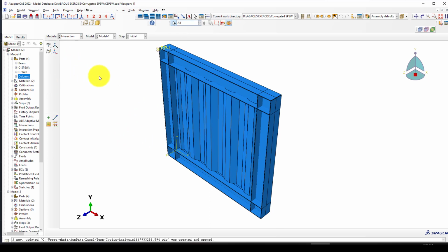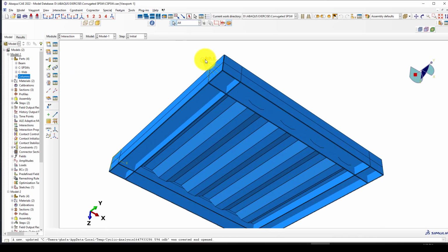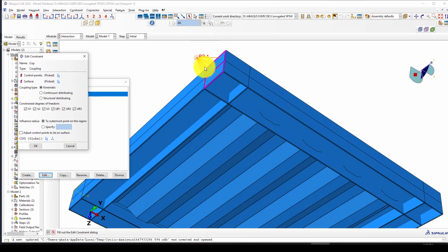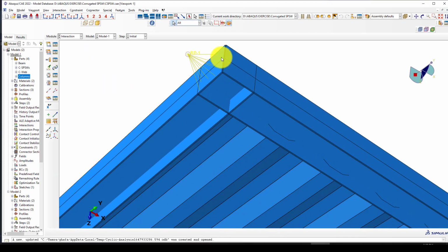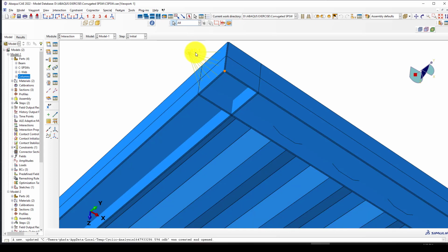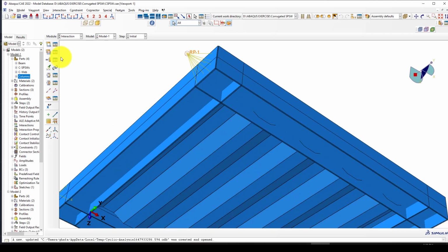We go to the interaction, so we create one point here. From this point you can create one point offset, and then define a set and a reference point, and then create a set called displacement or control point. So this is the control point you can see here, and then use a coupling method to couple this point with this region. Instead of applying load directly to the edge or the element, we take a little offset, and then we apply the load at that point.